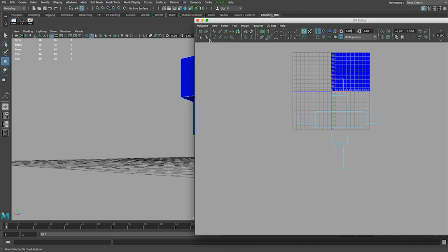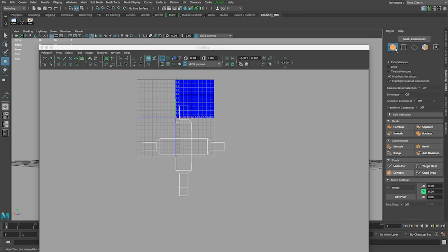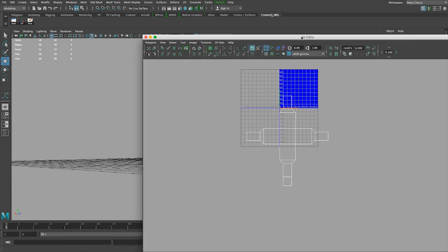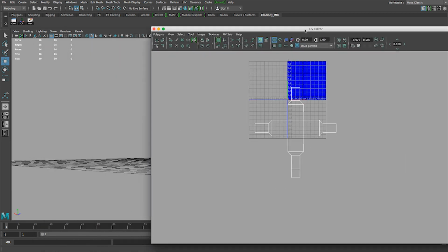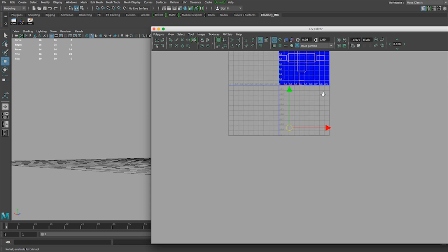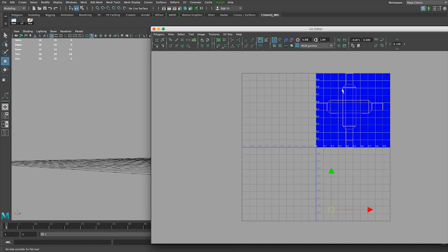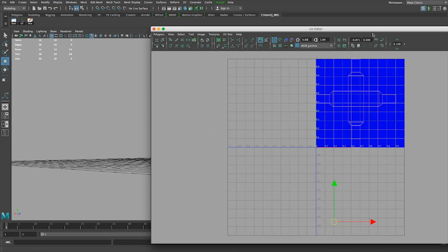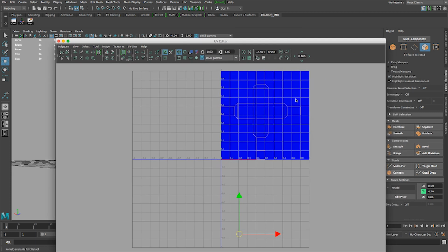And then let's say I am now pretty much happy with this. And I will just click back to object mode. And I will click again the arrange into space. And then it fits me into the UV map. So you get it like this. Now I'm not worried about losing all this space here because I know that there are going to be a lot more parts to this model and I'm going to put some parts here or here. But sometimes the trick would be afterwards this puzzle, fitting everything together.